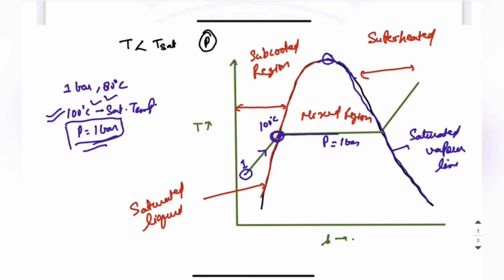This is the phase change region, and at this point the pressure and temperature both remain constant, and pressure is a function of temperature, or I can say temperature is a function of pressure. Meaning if pressure is fixed, then temperature is fixed, and it reaches the saturated vapor point. Now if you further increase the temperature, the water will reach the superheated state at constant pressure.